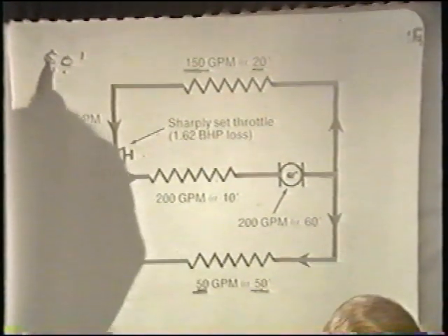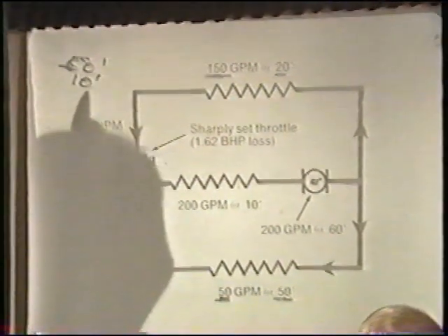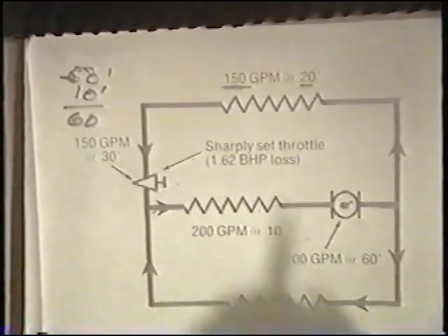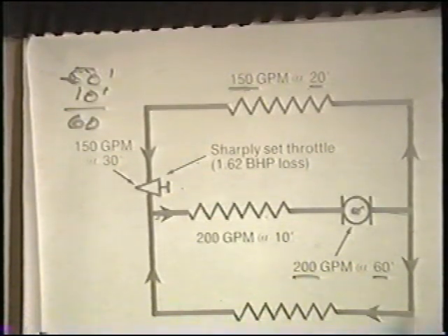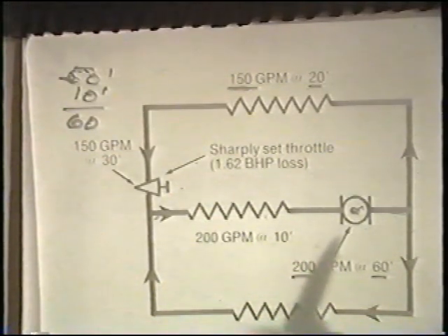No, this is 50 feet. So we have a total pump head need of 60 feet at 200 gallons per minute.